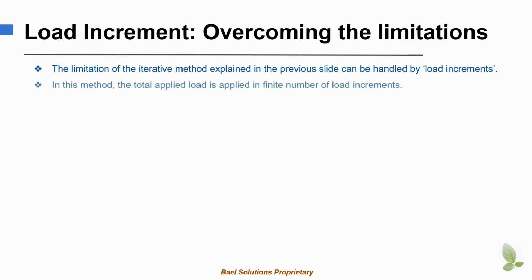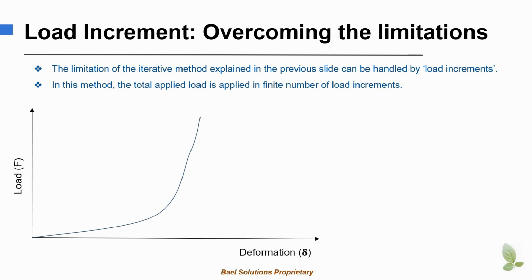In this method, the total load on the structure is applied in a finite number of load increments. We represent this method graphically. Let us consider the same load deformation curve of a highly nonlinear structure. Let F applied be the applied load, and delta actual be the actual deformations in the structure.